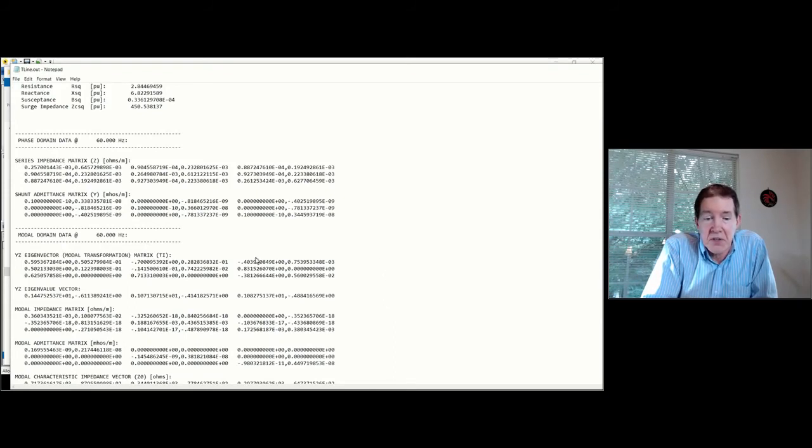You can notice here that this is not exactly set up where you have equal mutual values and equal self-impedance values, because again, this is not symmetrical construction. You have different spacing between A and B as opposed to A and C. You have this shunt admittance matrix. In this case, this is given in terms of Y. So what I calculated in the notes was X. You have to invert that, and that gives you Y.